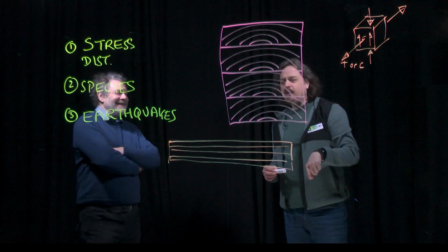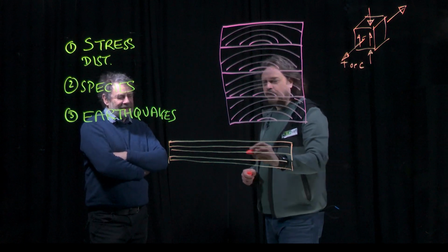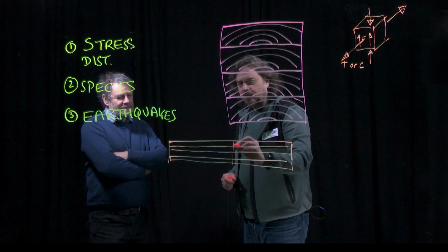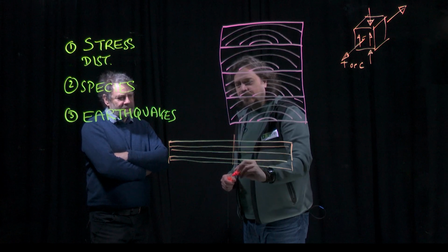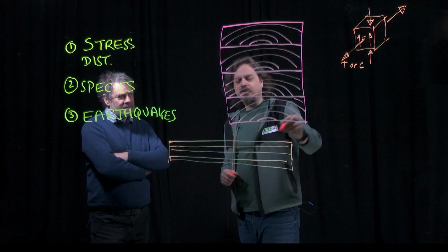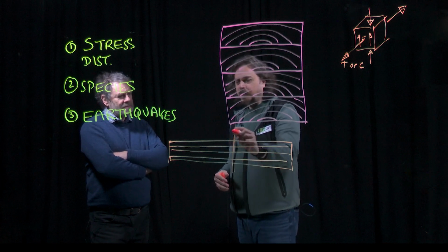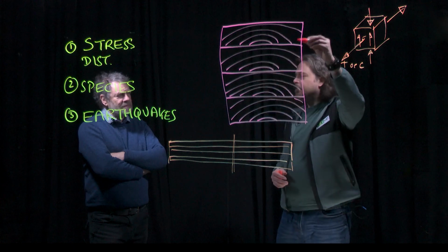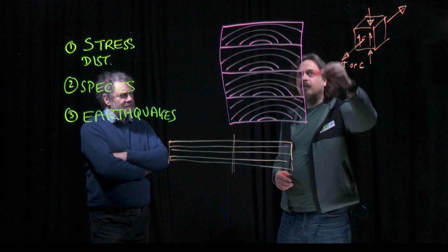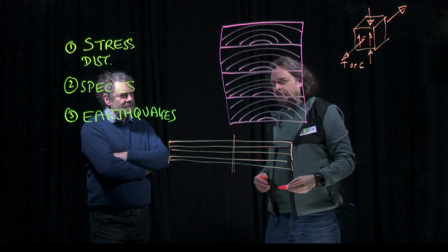Yeah, so if the beam is carrying forces, we can take a strip out, like this cross-section. We can imagine we've cut an imaginary piece out of the beam, and we can look at the equilibrium equation on this cross-section.